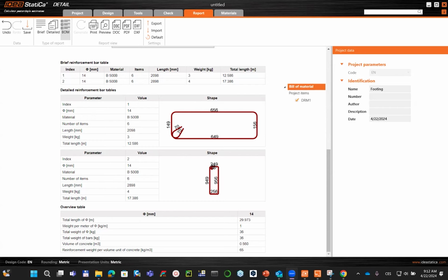Yeah. Okay. I see there is a possibility to introduce low concrete strength classes like C12/15, C16/20. Such compressive strength classes are not possible to be used in usual concrete applications, normal or pre-stressed, due to durability restrictions in Romania. Can you introduce somewhere the exposure classes X from the durability point of view in order to obtain the minimal concrete strength class?